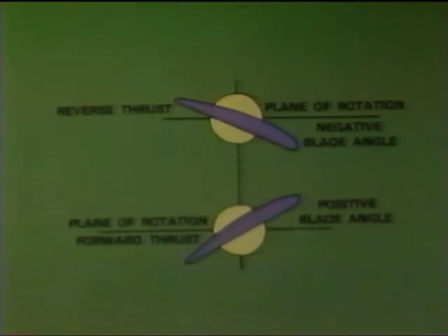When a propeller goes into reverse, the blades rotate below the low blade angle and into a negative angle of about -15 degrees. This forces air forward to provide negative thrust. The reversing operation is controlled in the cockpit by the throttles and is initiated by moving the throttles aft of the idle position. The further aft the throttles are moved, the greater the reverse thrust.